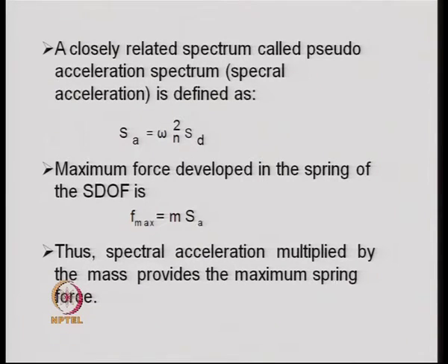A closely related spectrum called the pseudo acceleration spectrum, also called spectral acceleration, is defined as SA equal to omega n square Sd.